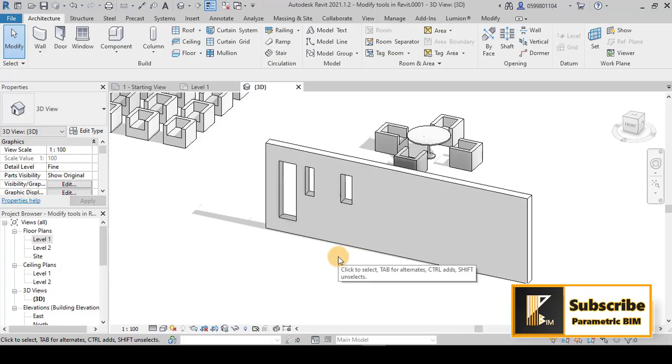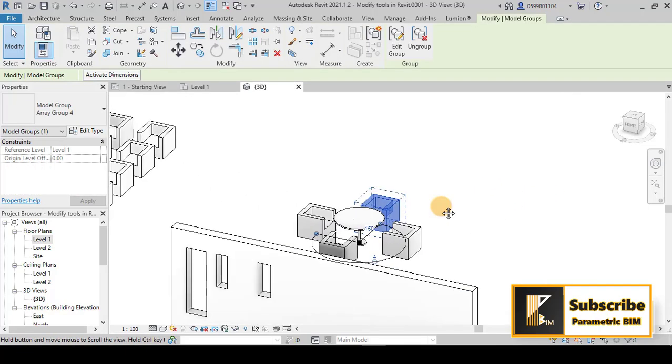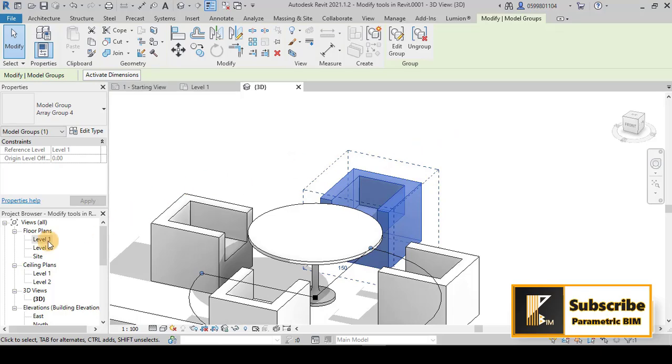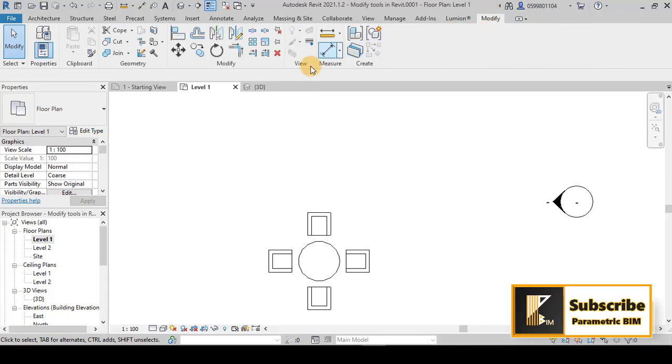For rotating objects in Revit, I will choose maybe this seat and I want to rotate it 90 degrees. You can simply go here to level 1 and then go to modify tools.